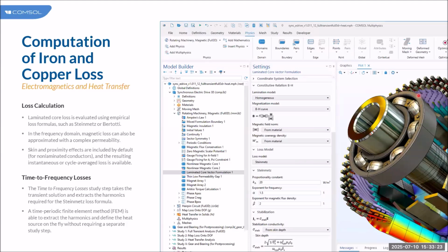And whenever we are simulating this particular electric motor, either we can simulate it in stationary mode, or in the transient mode, or in the frequency domain mode. Now, as you are aware, once you apply the AC to the conductors, your rotor will start moving slowly and it will come to a steady state. So it's a transient phenomenon. But after a while, once it comes to a steady state, the same is going to happen again and again.